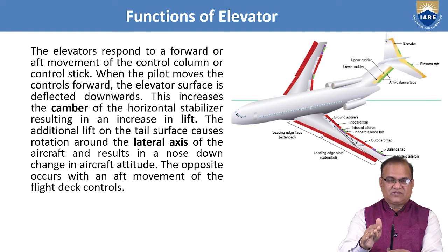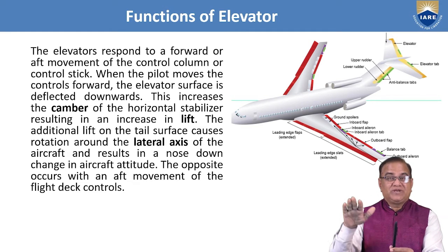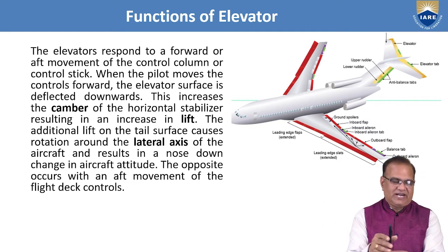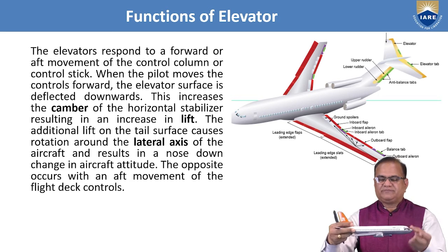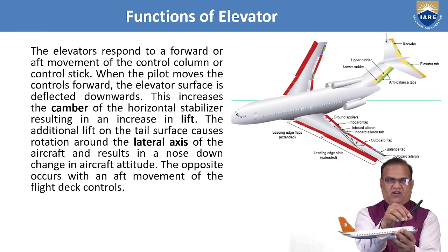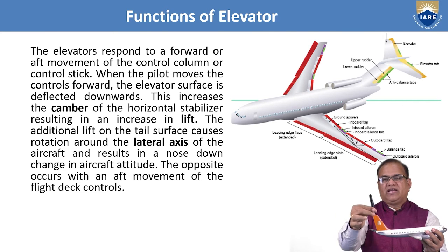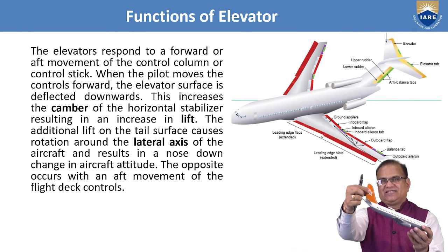In this case the elevator has to be deflected downward, so a lift will be generated upward, and it will try to move like this.